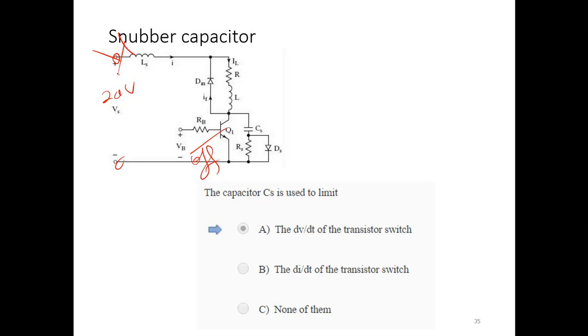Once your transistor is off, you go turn on the switch. Although there is no current here, there is a connection there. The capacitor is going to charge and see a voltage across this. The capacitor will be very much a short at the beginning. As a result, the device here is going to see a large dV/dt. Suddenly it had no voltage, and suddenly it got 200 volts, coming instantaneously. That will damage that device, dV/dt.